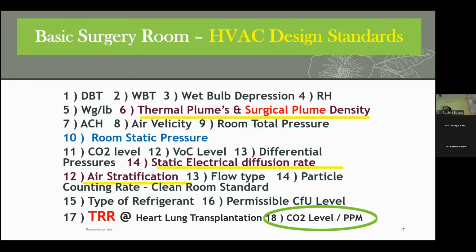So when you are designing a surgery room, if you don't consider the surgical plume and its density, it depends on what wattage of machine they are using. Different surgeries use different wattage of diathermy machine. This is very important, and the heat which is generated over the patient has to be removed. This is a big challenge for a surgery room.